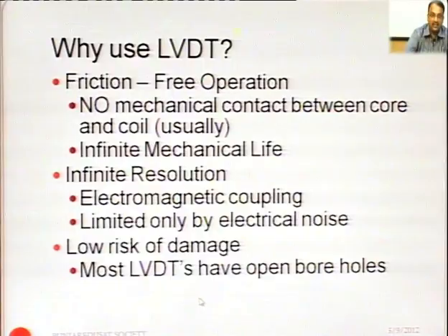Why use LVDT? What are the advantages of LVDT? First is friction free operation. There is no mechanical contact between core and coil, so there is no chance of any type of friction. Infinite mechanical life, infinite resolution, electromagnetic coupling limited only by electrical noise, low risk of damage.